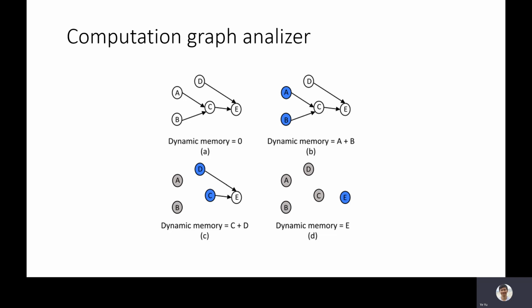The dynamic memory allocation is monitored throughout the DAG traversal, and the maximum dynamic memory demand sets the lower bound for the on-chip buffer size of the accelerator if all the intermediate outputs or the activations need to be stored in the on-chip buffer.